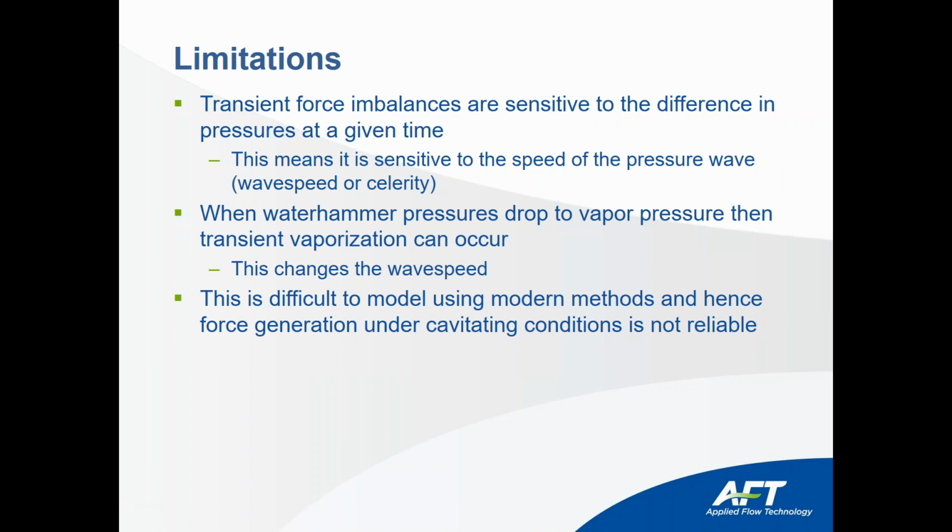It is very important in the method, when you have the pressure going under the vapor pressure, you can have vaporization and bubbles, and these bubbles can collapse due to the high pressure. This is a very difficult model using these methods, and hence force calculation under cavitation conditions is not reliable.